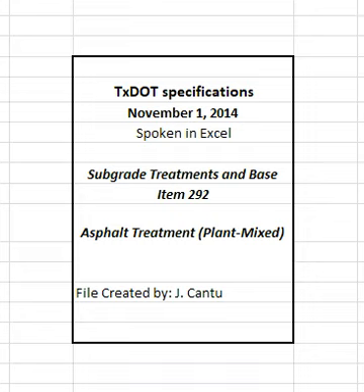2.5 Additives. When shown on the plans, use the type and rate of additive specified. Other additives that facilitate mixing or improve the quality of the mix may be allowed when approved. If lime or a liquid anti-stripping agent is used, add in accordance with item 301, asphalt anti-stripping agents. Do not add lime directly into the mixing drum of any plant where lime is removed through the exhaust stream unless the plant has a baghouse or dust collection system that reintroduces the fines back into the drum.